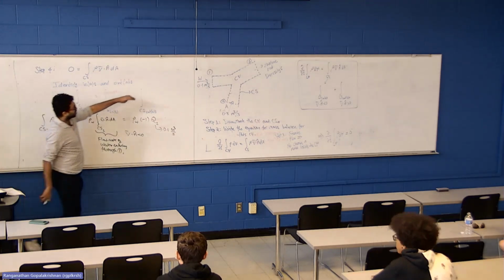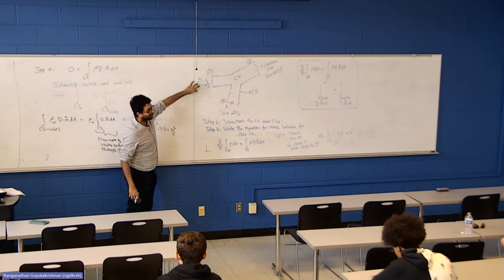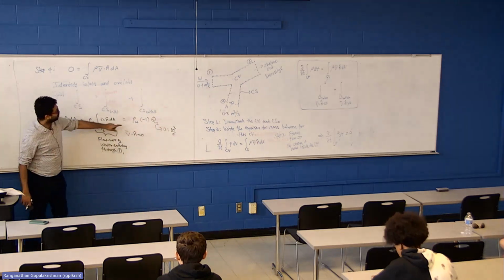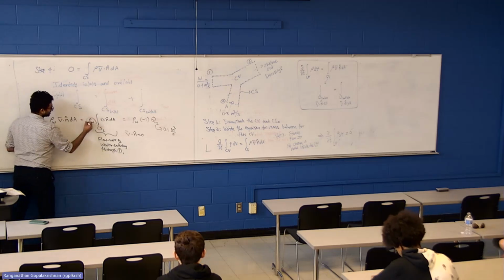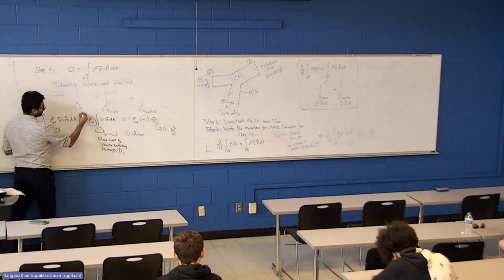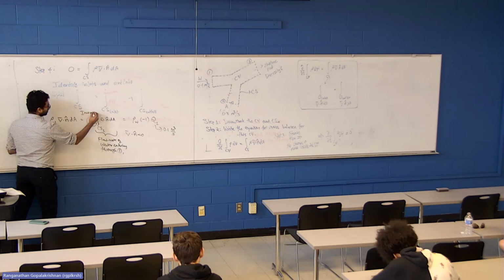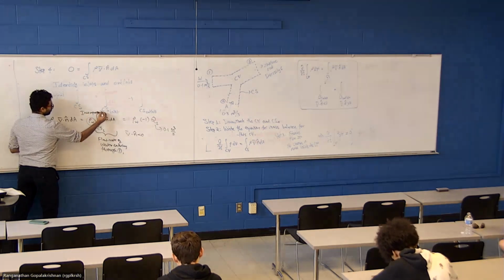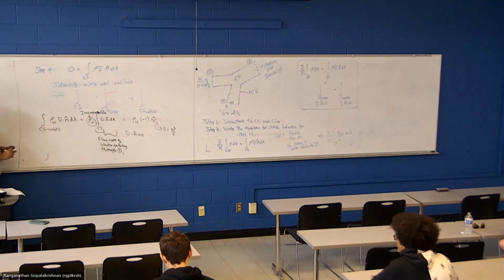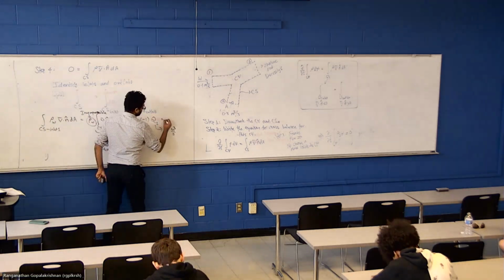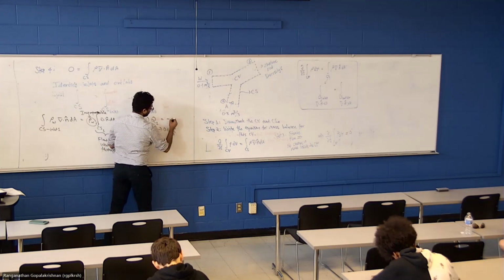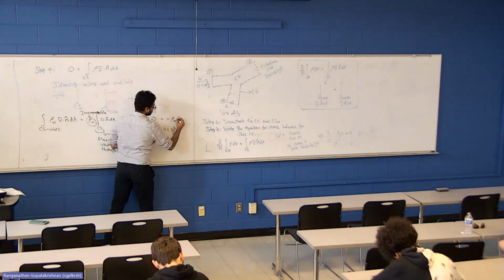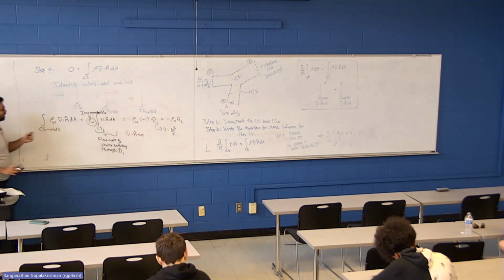We are given already the flow rate. If we were told in terms of velocity, we would have done that calculation. But we just use the flow rate directly once we pull the density out of the integral because we have an incompressible fluid. So I have minus rho W times Q1, and keep it like that.